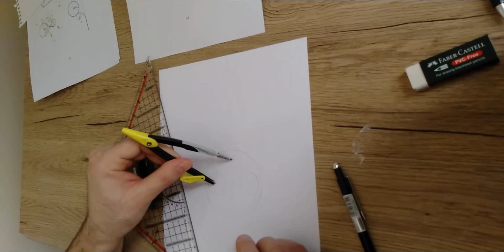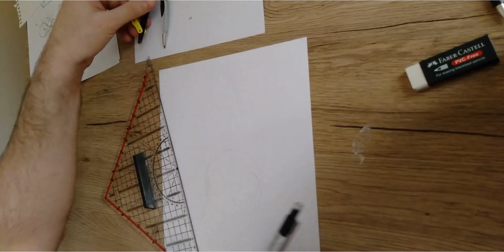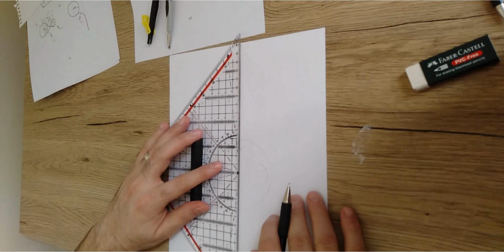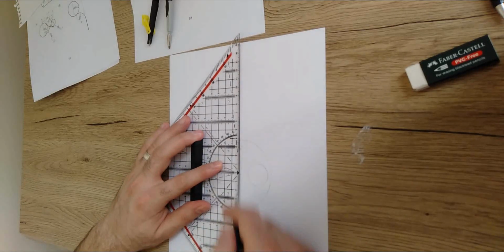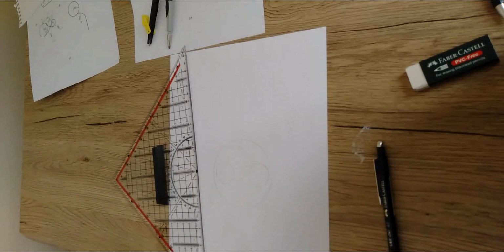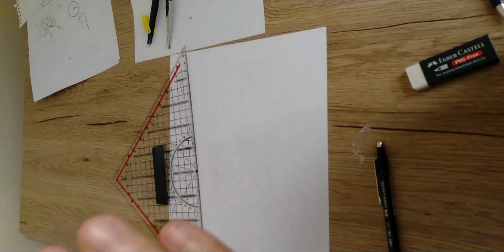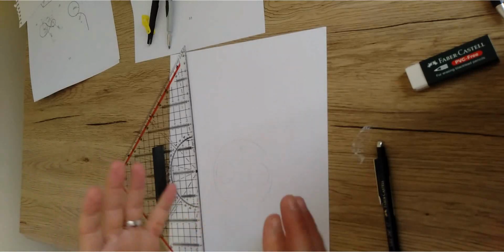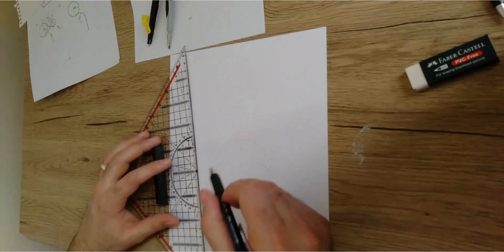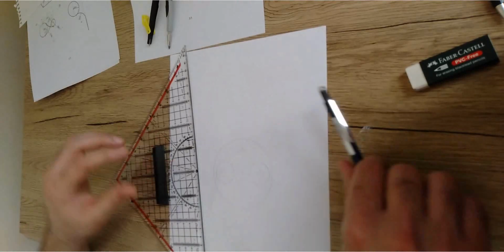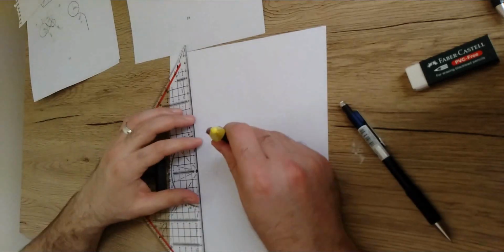If your drawing is accurate, these two curves should intersect over the vertical line through the center point of the big circle. Why? Because you are opening with 37 from the right and the left. So definitely this intersection point should be located in the middle between these two centers. And this is what we got here. It is typically over the vertical line. This should be the center of this curve.